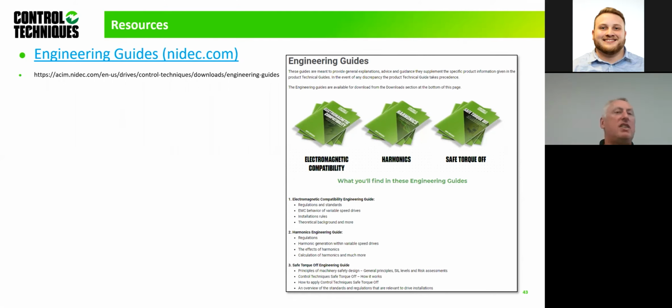and the beauty about the generator in some respects is you've got no MV, no primary side. What you've got is a local point of common coupling. The beauty of that is the owner of the LV is your customer, the site. If he has high distortion and it doesn't meet IEEE 519, but everything runs satisfactorily, he does not need to change anything. And you find this a lot in the steel mills and whatever, because their system's immune, it works okay.